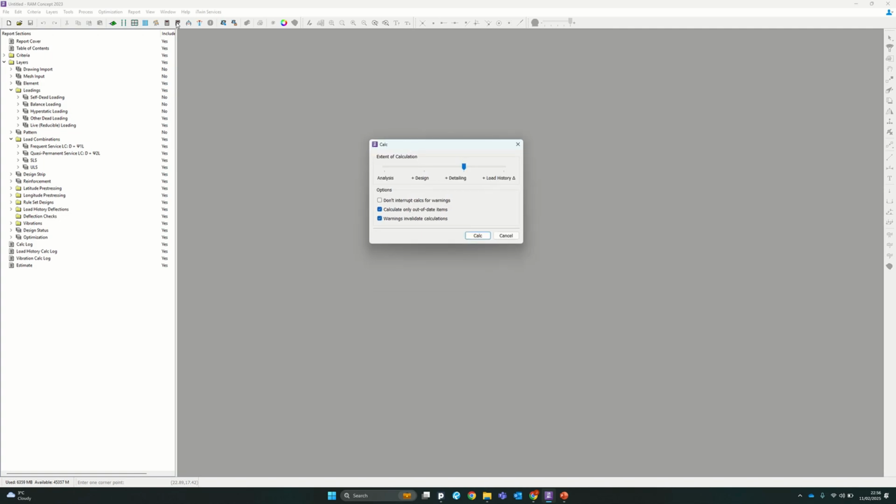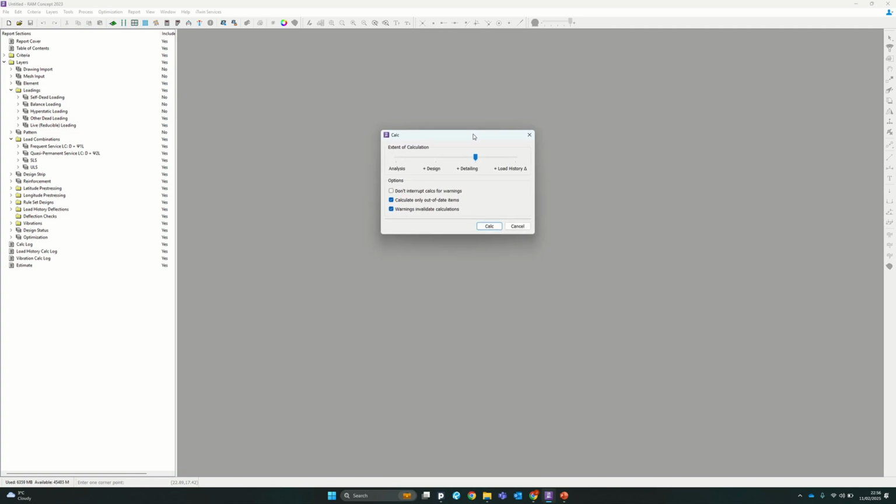When you click on these calculation options, it comes up with a menu like this, and it gives you these 4 options. Depending on what level of complexity you're looking for depends on which one you click on. Because I haven't modeled any of the design strips or any of the reinforcement, it doesn't have the information for these last 3. However, you can do a basic analysis.